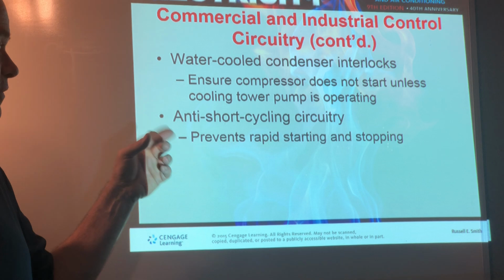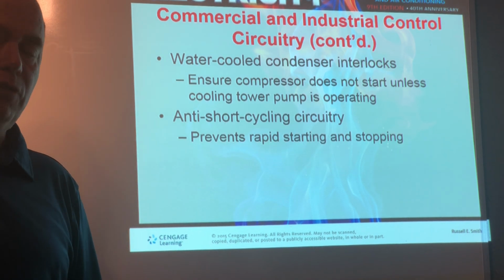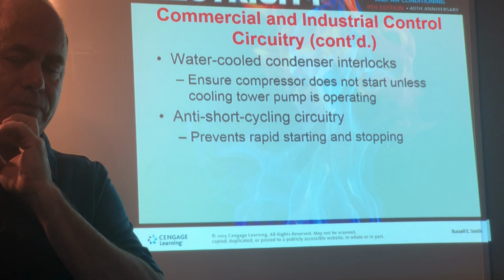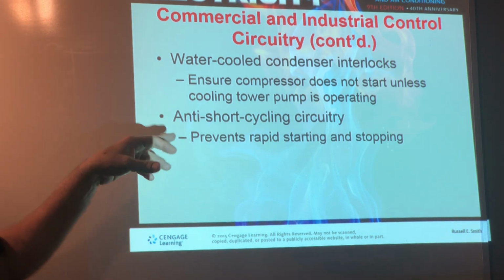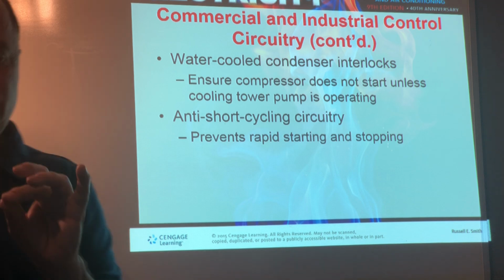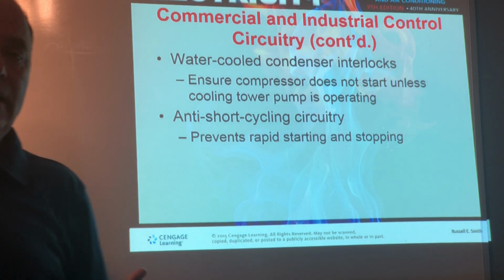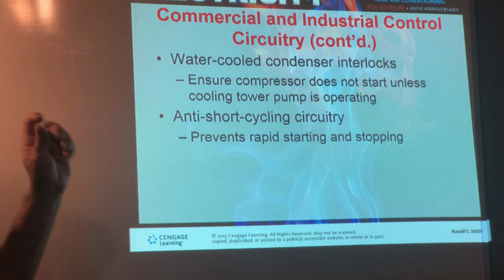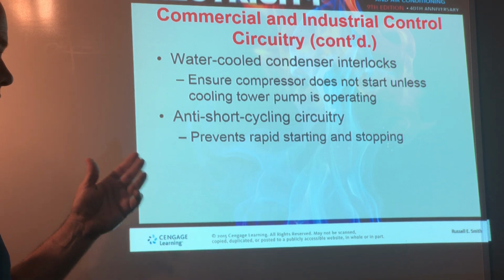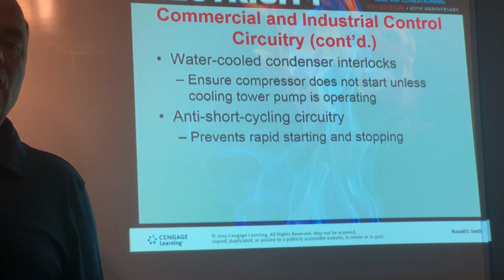And more, we have this concept all throughout the industry where we're not going to let things stop real quick. That kind of can ruin things. We're going to let them sit off for a little bit. And even just off topic a little bit, new thermostats in refrigeration, little tiny commercial boxes, actually will have that built into it, where when the thermostat opens for, let's say, a little reaching cooler, it's not going to let it close again for a couple of minutes, just to make sure that we don't overload the compressor.